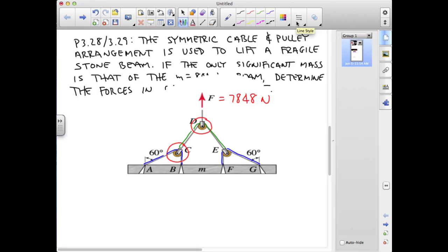Okay, so what can I say about this? Well, we said last time that if we considered a coordinate system for one of these shackles where we had a tangent normal system and the tangent was coincident with the line of action of the cable attached to the shackle, then the fact that we had the same tension on either side of the cable ACB meant that the line of action that I've shown here as a dashed line has to bisect that angle. So the angle made by this segment ACB is 60 degrees. That means that these two angles have to both be 30 degrees.